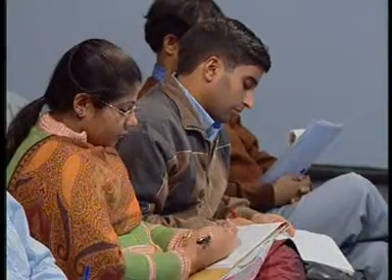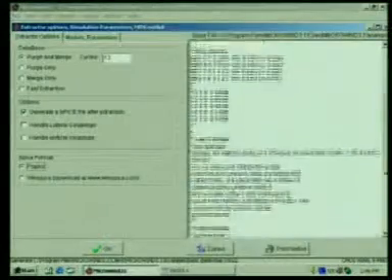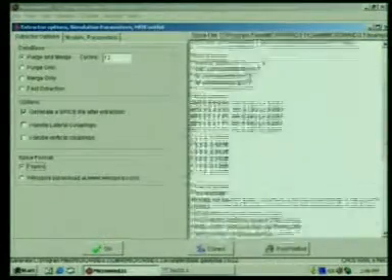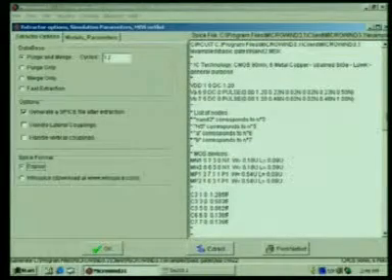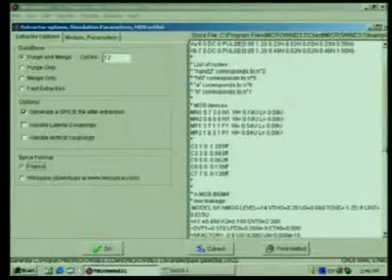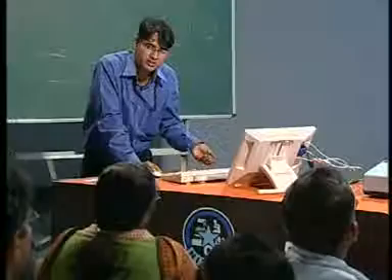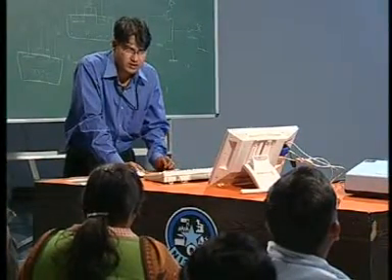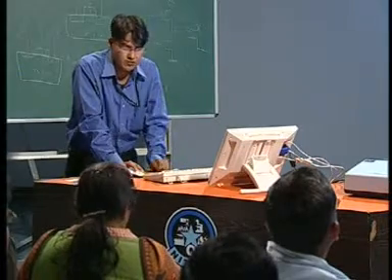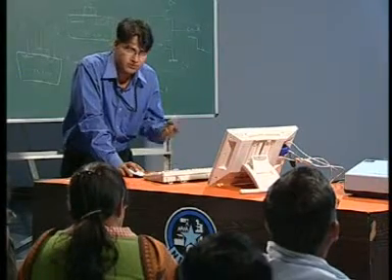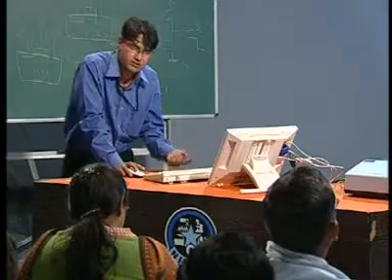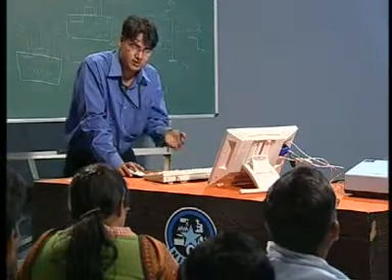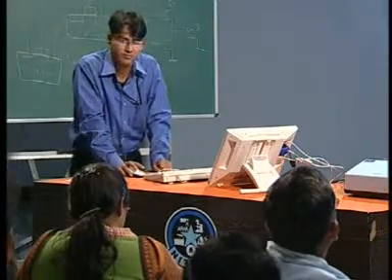PSpice extract. See, this is the code. You can import this into PSpice, and you can go for transient analysis, DC sweep, AC sweep, whatever analysis, Monte Carlo analysis, you can go for there also, because no designer relies on one single software. You have to simulate with the help of different kinds of algorithms. So there is that kind of flexibility here.